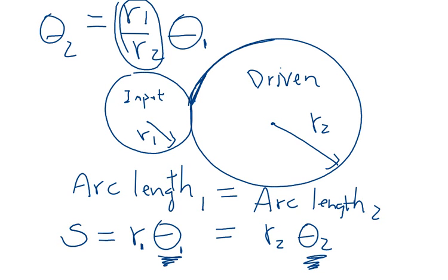In your high gear, gear 2 is now smaller than gear 1, your input gear. So your engine doesn't have to run very fast in order for your car to be moving at a very fast speed, because the amount that your driven gear is going to rotate by is much larger than the amount that your input gear rotates by.